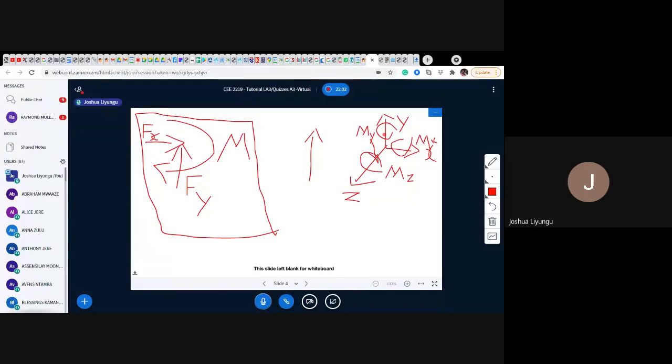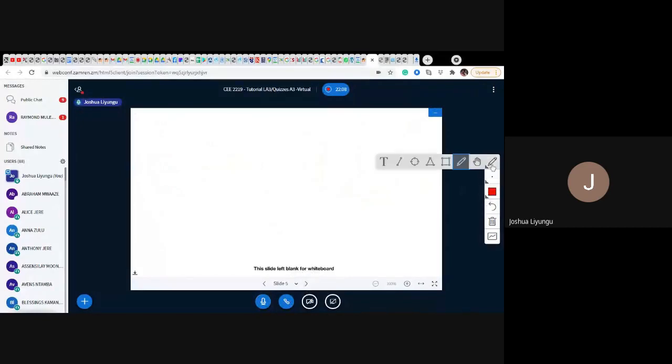So the first thing that you need to do, if you have been given a body, as an example, a truss, then of course it is being supported, maybe by a pin. The first thing that I need to do, if it's a pin, is model my reactions. If it's a pin, I need two, the one horizontal, the one vertical, which is the F in the Y and the F in the X.